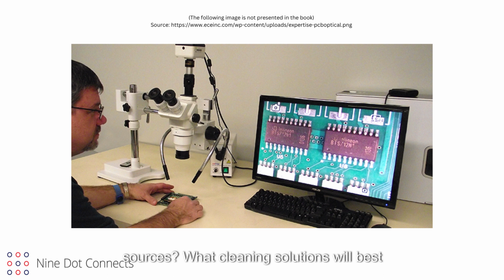What cleaning solutions will best remove contaminants? Will the solutions require board agitation? Is a vapor phase degreaser the best method? Is a chemical solution and ultrasonic the best cleaning solution? What is required to remove the remaining cleaning solution? Are there any devices that may be damaged with the selected cleaning technique? What is the size and shape of the PCB and mounted components?